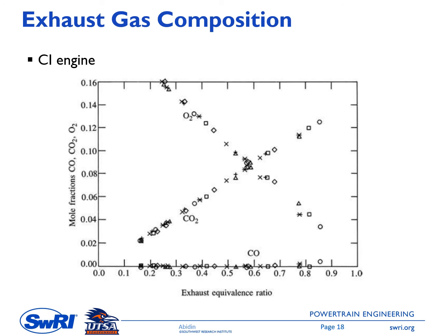And this is the exhaust gas composition for compression ignition engine. As you might know, the diesel engine operates under lean mixture condition. So the data that we have here is with phi less than 1. Although I can tell you that several years ago, we have done research looking at the stoichiometric diesel combustion, but it was still under research.